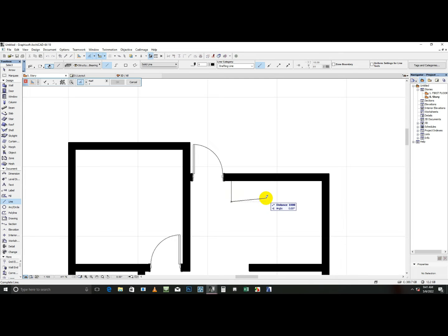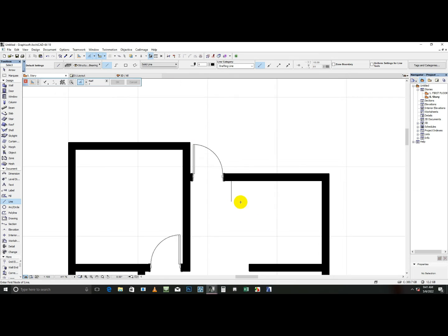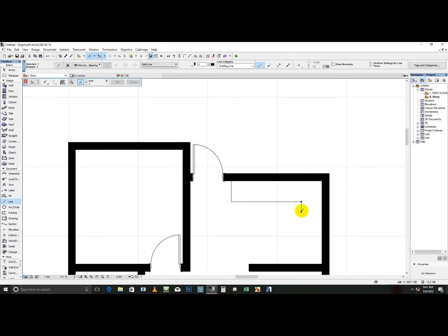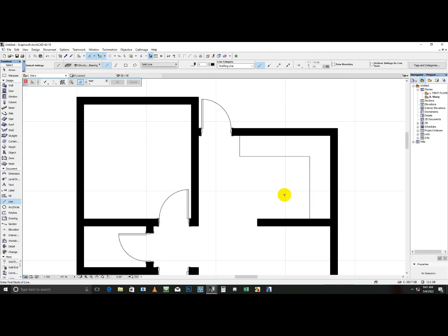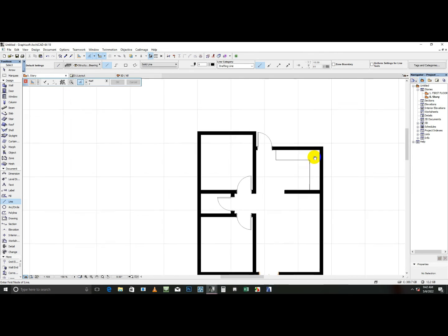I'm using line work, okay? I've highlighted on my line, double clicked on that. Line has no match, so from there to here, 600. Okay, just click, drag on, highlight on the edge, and cut as I showed you earlier. Let me delete that. I push this to the side. Okay, so that's my kitchen worktop. All right, my kitchen worktop.